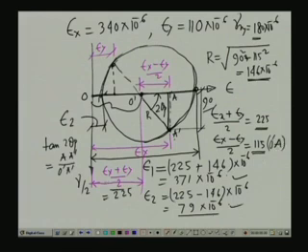So, 90 by 115, tan inverse of that gives us the value of 38 degree. So 2 theta p is equal to 38 degree, and thereby theta p is equal to 19 degree. So, this is the orientation along which the maximum principal strain occurs. Now, what we need to do is to evaluate the strains at a direction which is oriented at an angle of 30 degree with reference to the reference x axis.